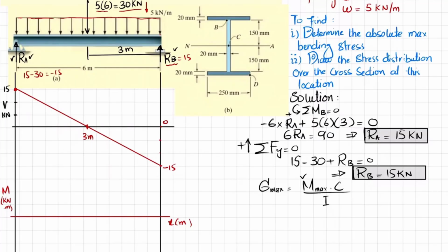So let each division be, let's say 5. So this will be 20 kilonewton and 22 will be in between these two. So you will have a point like this. Let this be 22.5. Since this shear force line is a 1 degree line and the slope is decreasing, the bending moment will be a 2nd degree curve and it will be clockwise. So we will draw the bending moment like this one.